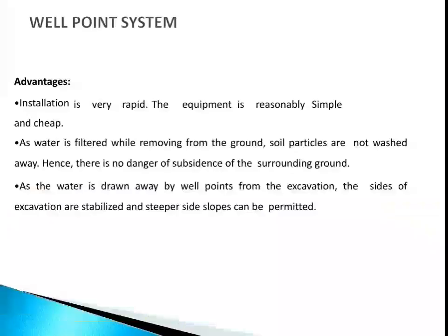Next, advantages. Installation is very rapid. The equipment is reasonably simple and cheap. As water is filtered while being removed from the ground, soil particles are not washed away, hence there is no danger of subsidence of the surrounding ground. As the water is drawn away by the well points from the excavation, the sides of the excavation are stabilized and steeper side slopes can be permitted.